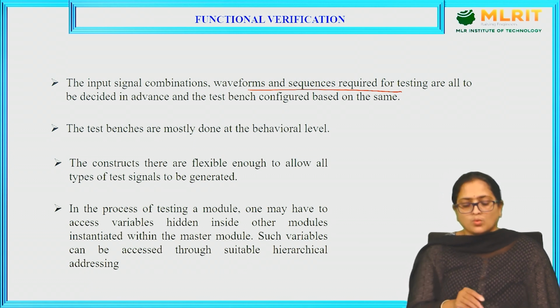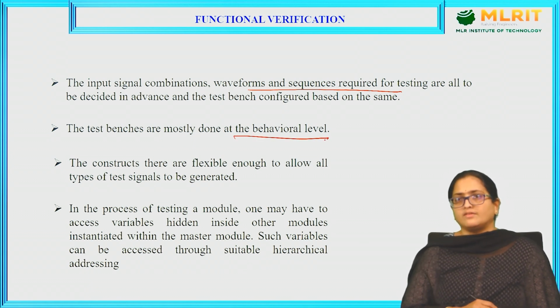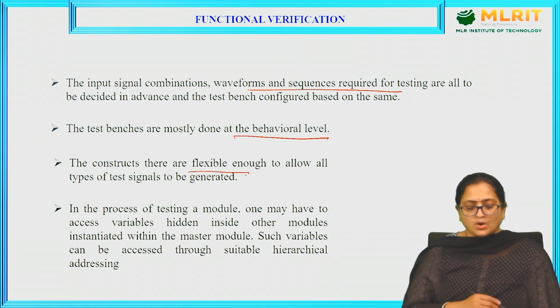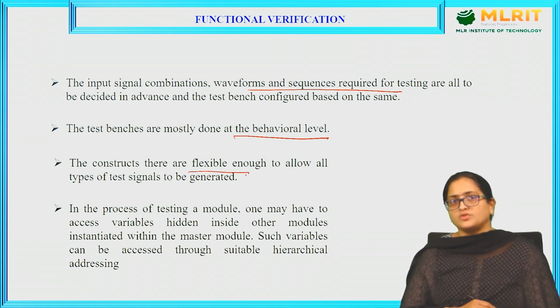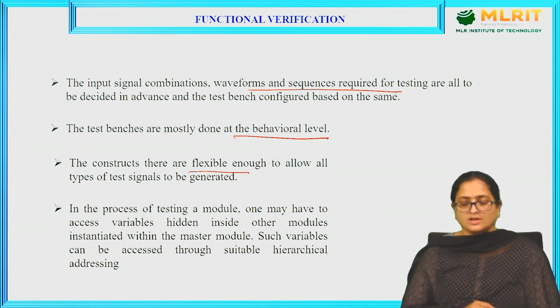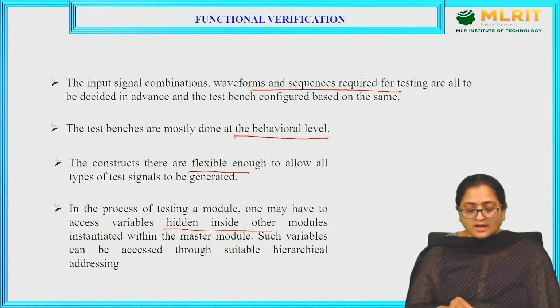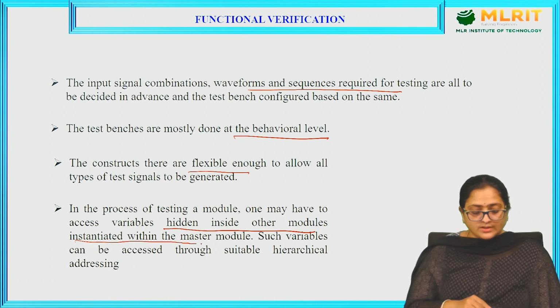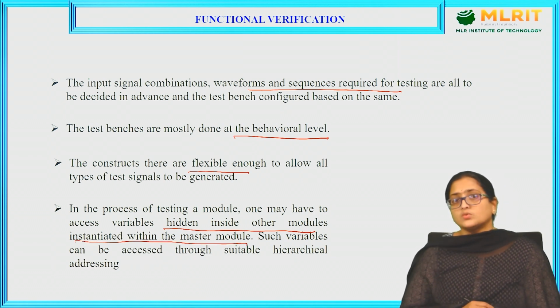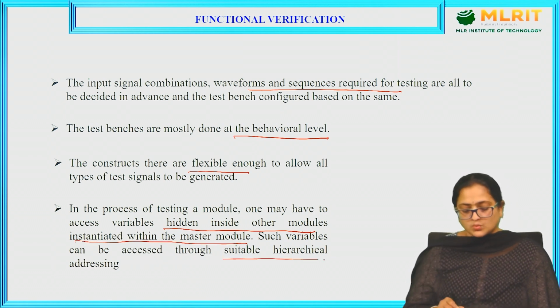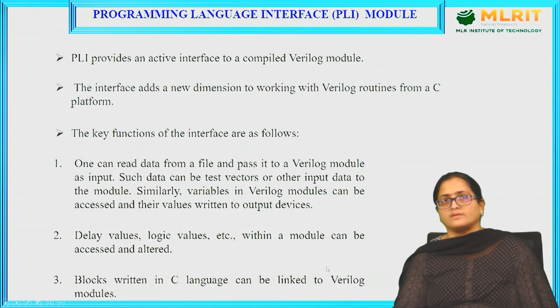The test is mostly done at a behavioral level. The constructs are flexible enough to allow all types of signals to be generated. In this process of testing a module, one may have to access variables hidden inside other modules instantiated within the master module. Such variables can be accessed through suitable hierarchical addressing.